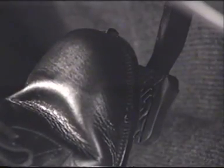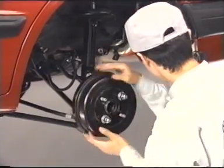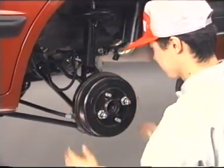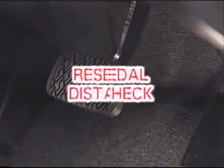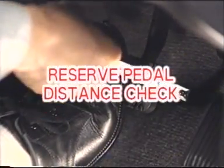Finally, check the brake operation. Depress the brake pedal a few times and confirm that both drums rotate smoothly. Confirm that the reserve pedal distance is within specification.